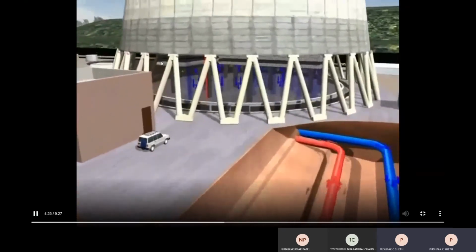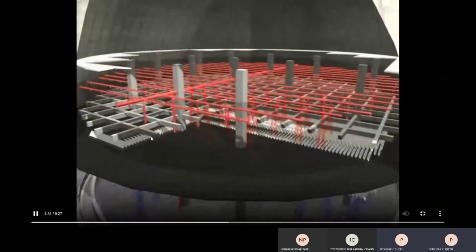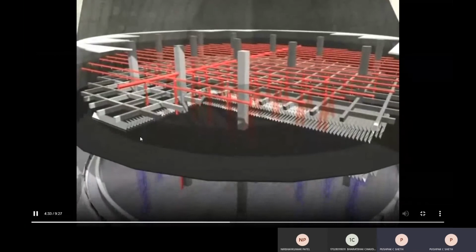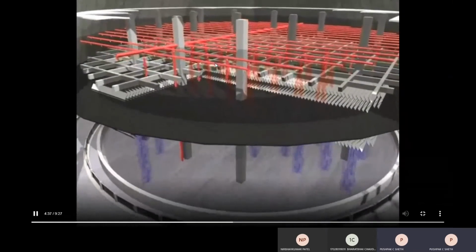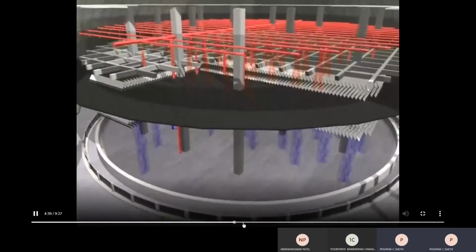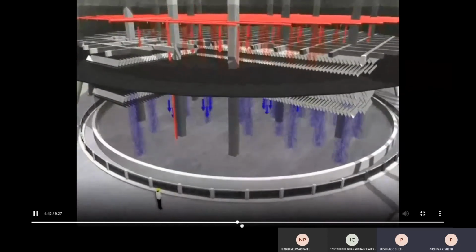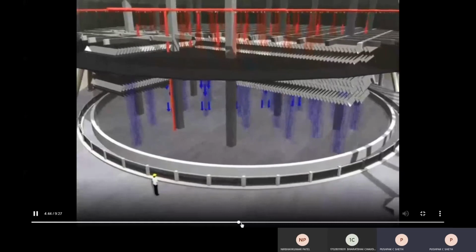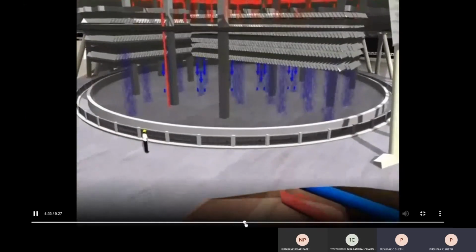The hot water is going on, and in the cooling tower, the water is spread from the top. That means atomization of the water is taking place, and air, due to the pressure difference, is going up. So it will cool the water, right? And that cooled water is again utilized in the condenser for the condensation of the steam, which is coming out from the steam turbine.